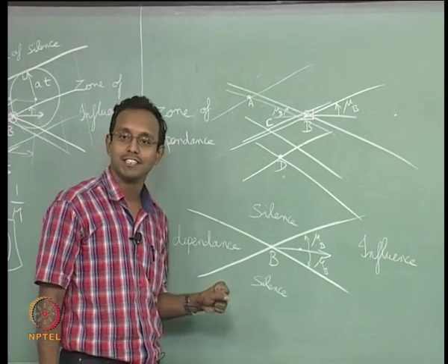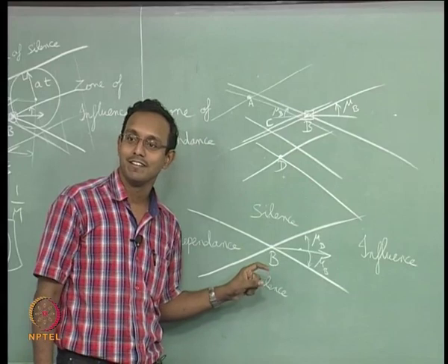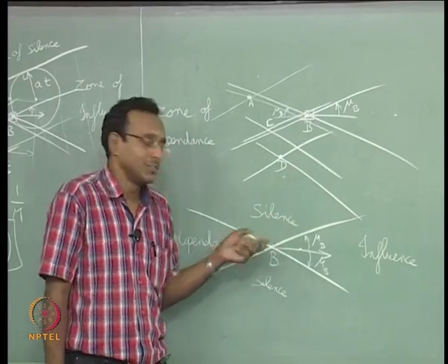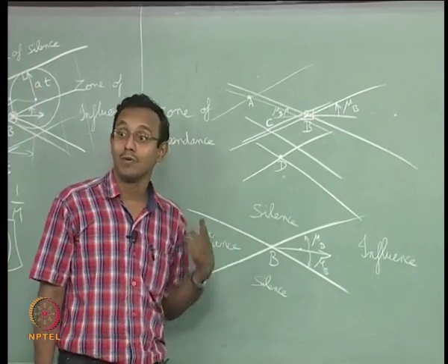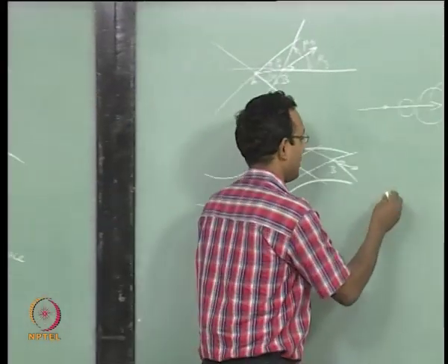If it is subsonic, there is no solution for this. Sin inverse 1 by m, with m less than 1, right. So, sin inverse of something more than 1, there is no solution for it. So, this particular picture does not make sense for subsonic conditions. Why? We go back and recall the animation.